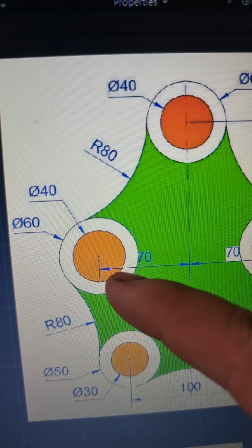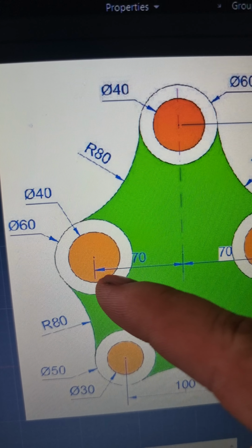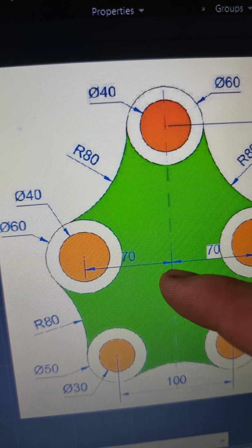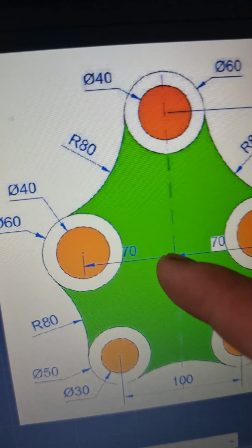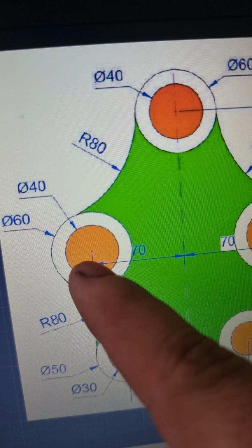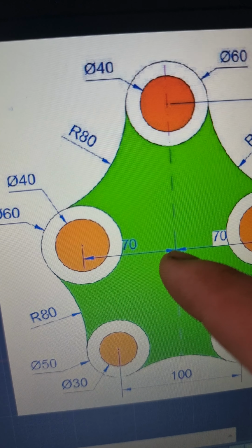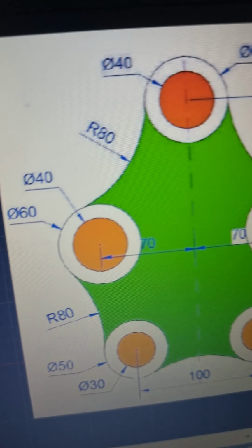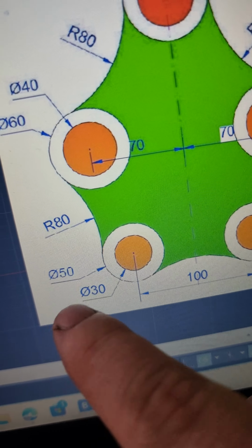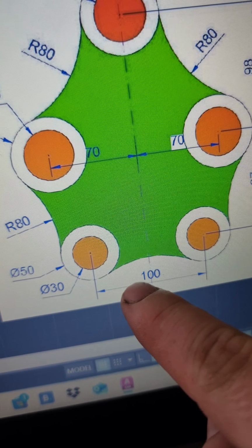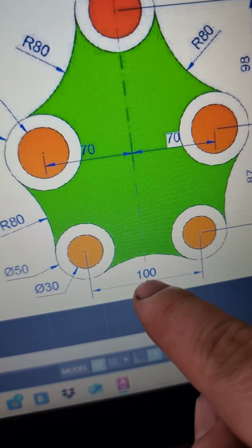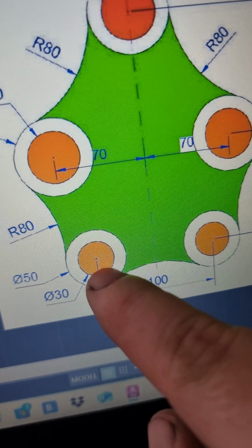And then this one does have an arrow, pointing to that point with the other side of the arrow, and there's a little line there, that's 70. From that point to here, that's 70. And then down here, here's another distance, because there's no symbol, there's no R, so it's just a number. When it's just a number, it's a distance.